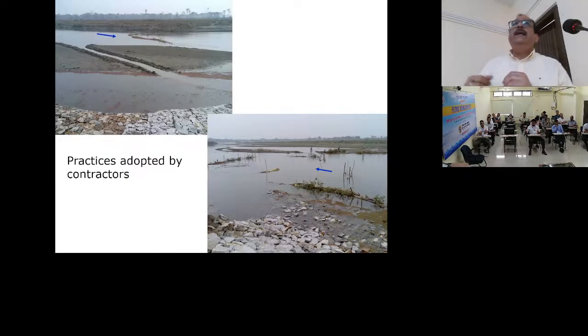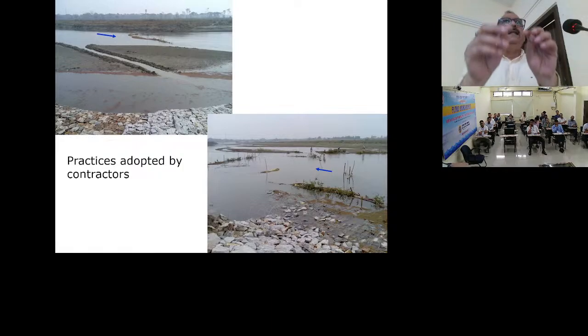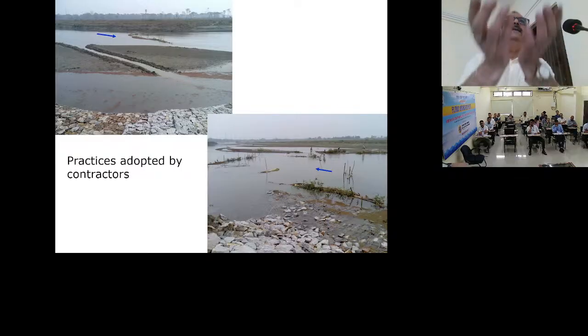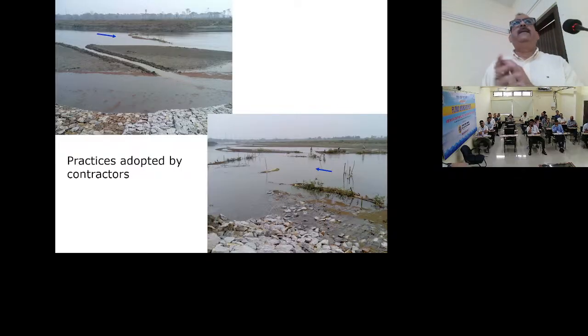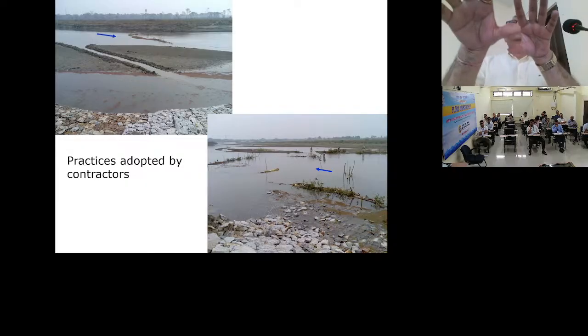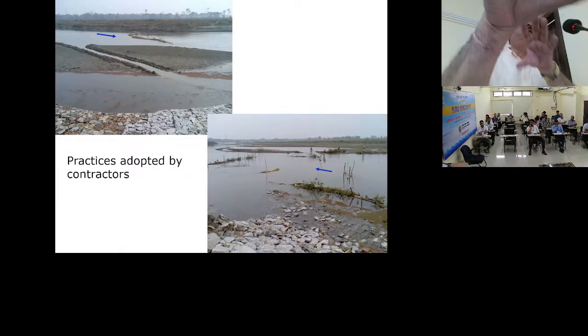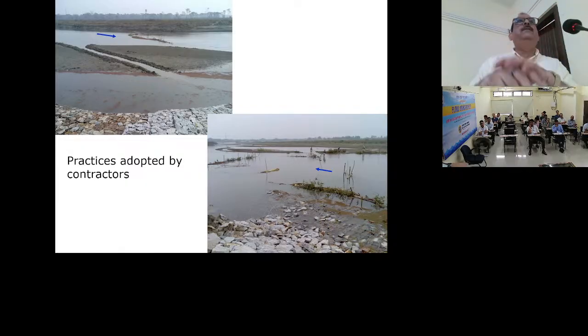What they are doing, they are inviting the river towards the bank. They are decreasing river velocity. So sediments are deposited at the river bank. The river bed is rising at the near bank. And they are putting their boulders there. Now they have to use less volume of boulder. They are saving their money.